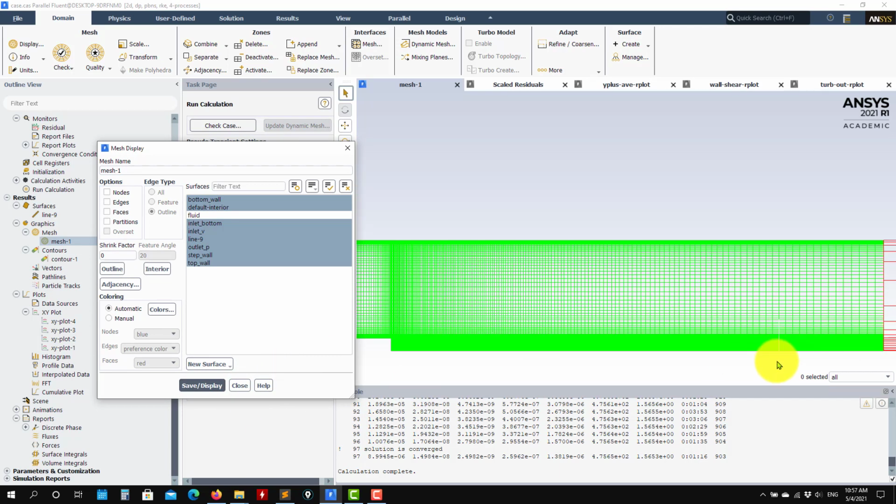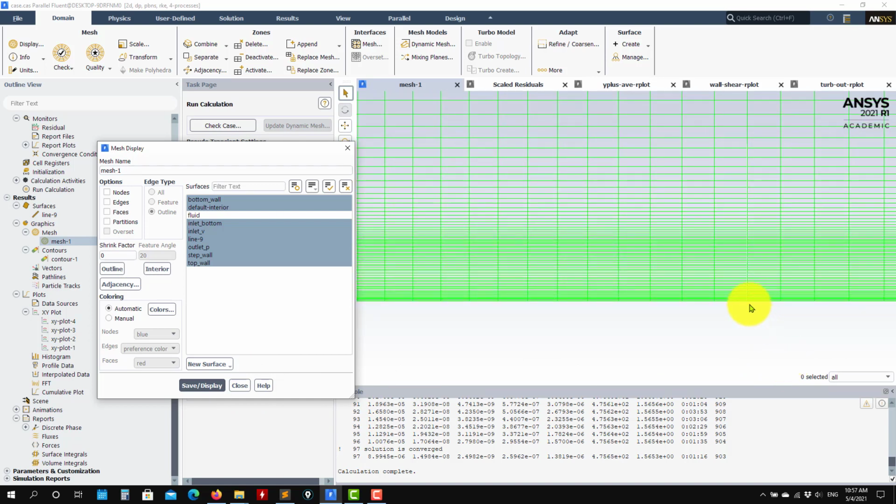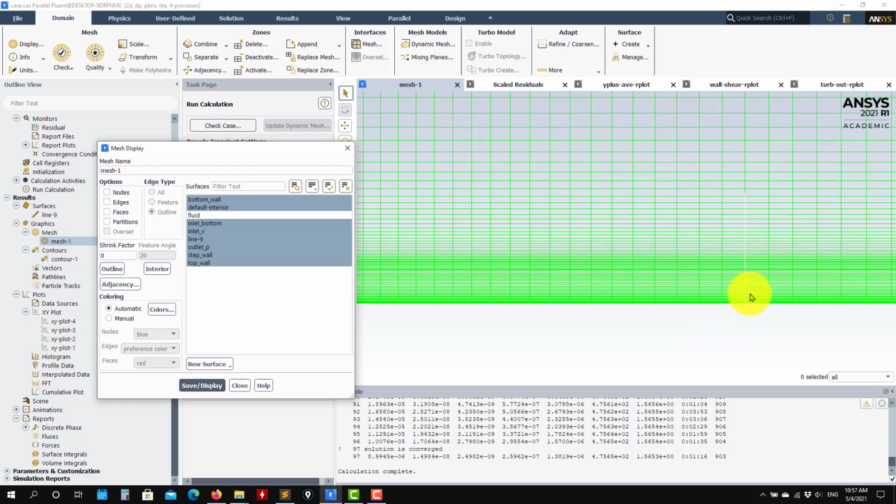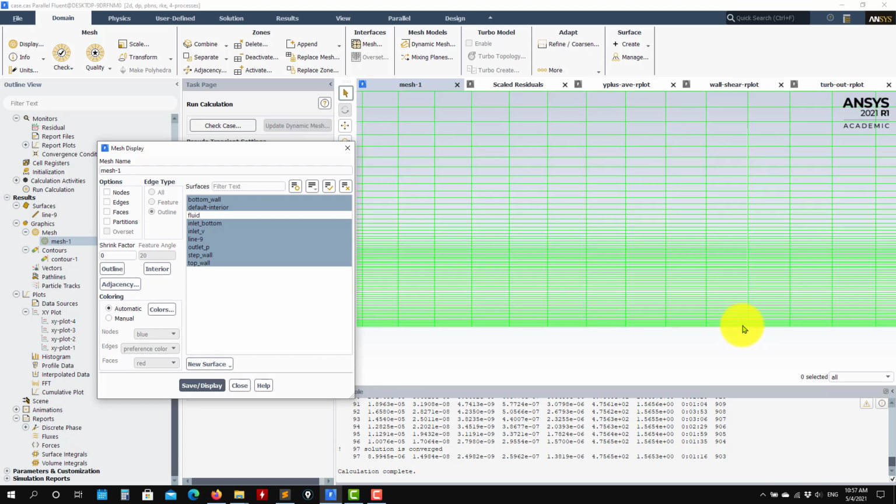Okay, so this is what you do. Remember, to do those plots, you need to compute wall shear stress. Then you sample in a line that needs to be normal to the wall. In this case, a straight wall, there is no problem, but if you have curvature, you have the geometry, so you know how to generate this line. Then you sample the velocity in this line and compute y plus in this line.